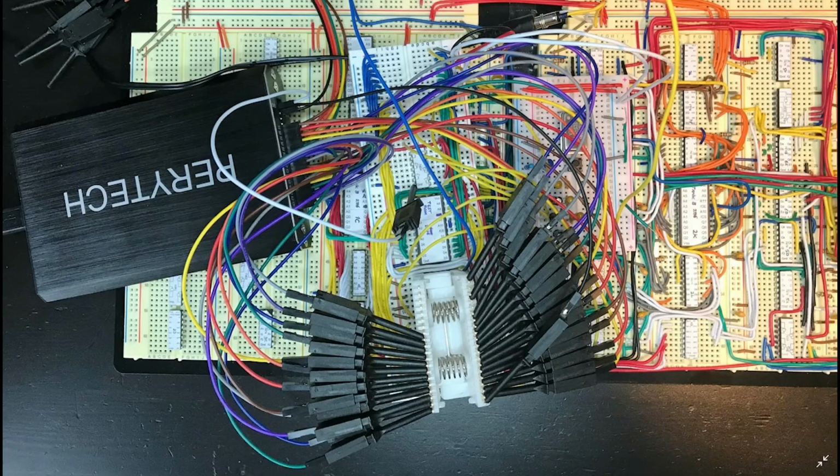So that's the CPU there, with on this side the address lines going from A0 up to A15. That ends about there. This is the ground, and then from there we've got the data lines D0 up to D7, and then we've got the reset line is that one, we've got the clock input is that one, and then this one is the read-write pin. So we're monitoring all of those at 1 megahertz so we can see how everything's operating.